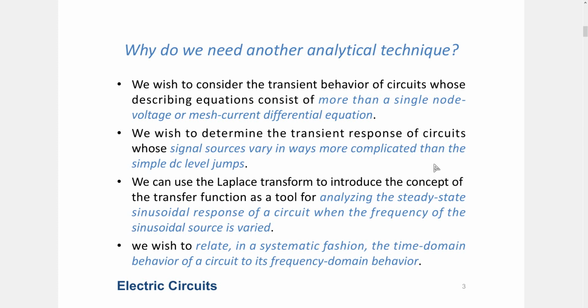However, in analytical terms, in order to estimate what will happen when you turn on a switch, we use traditional circuit analysis methods such as KCL and KVL, and they yield integral differential equations of first, second, or third order. I mean, you will be dealing with time domain equations which are hard to solve.